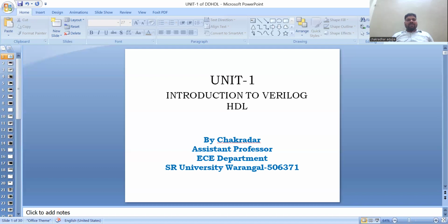The basic steps involved in synthesis are: writing synthesizable Verilog code, ensuring that the code is written in a synthesizable form. Constructs such as initial blocks, test benches, or delays are not synthesizable and should be avoided. Using a synthesis tool like Xilinx Vivado, Synopsys Design Compiler, or Intel Quartus to perform synthesis. Generating a netlist, where the tool generates a netlist, a gate level representation of your design. Implementation on FPGA or ASIC, where the netlist can be mapped onto specific hardware, either an FPGA or an ASIC fabrication, based on the need.